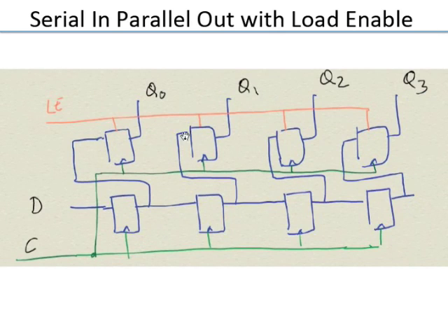So now let's come back to our problem. We had the original shift register. Now what we do is, we have this data, and this is the final parallel data we are concerned with. We'll isolate that from the internals of the shift register by this bank of flops. So here there will be a load enable. Once I shift it, my load enable will go high, and then this data gets captured into this. Then it comes out. So basically you need a controller which can orchestrate all these things. There is a little controller which is making sure the load enable goes high at the right time and so on.